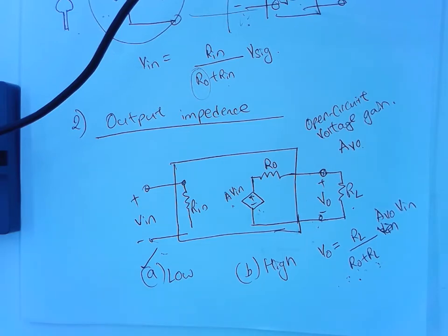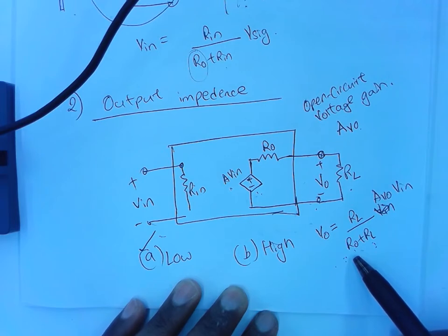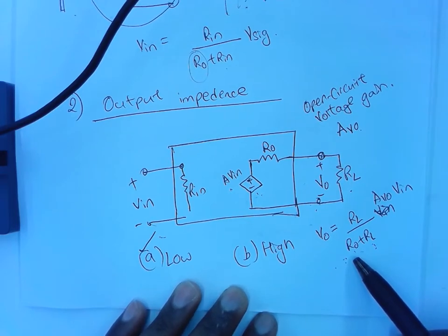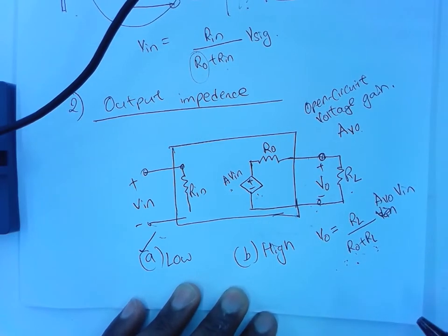So usually when you design, let's say, speakers, you'll have something called a preamp, which will just amplify the voltage, and then there will be the power amplifier, which will amplify the power. You'll try to do it in two stages, because usually you cannot have both at the same time, and we'll see that when we're designing amplifiers. So the bottom line is, the smaller RL is, the smaller RO should be. Ideally, RO should be 0 so that you don't care about RL, but in general that's not possible. Any questions here?